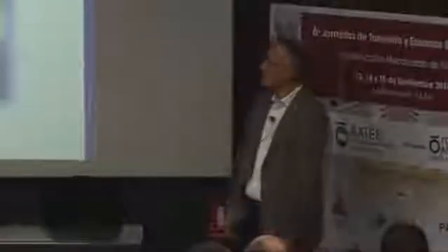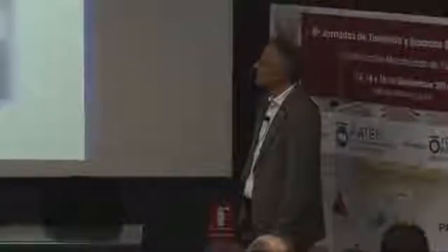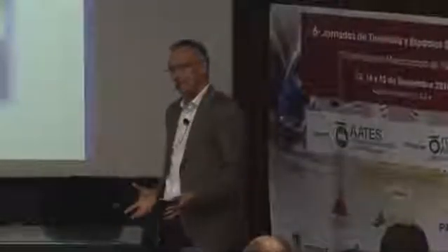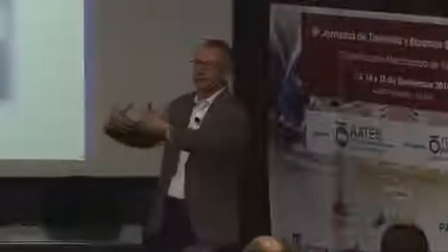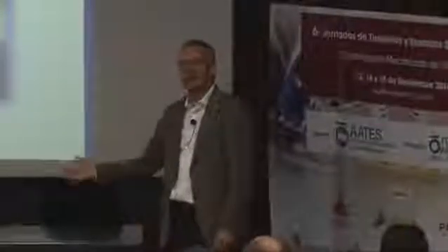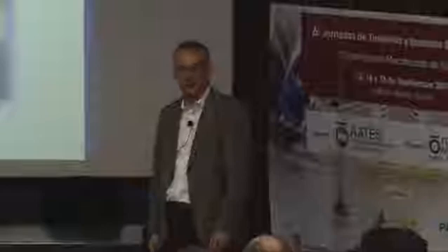There's one possibility to get control again of your tunnel face, and that's what we practically fill. We use artificial soil and fill practically from inside, from behind, from the bulkhead. We fill this artificial soil into the excavation chamber, and it's heavier than the bentonite suspension. So it practically fills up the lower levels first, and then you can pump with increasing pressure. You can fill it up to the surface and have practically the whole bentonite suspension exchanged against this artificial soil.